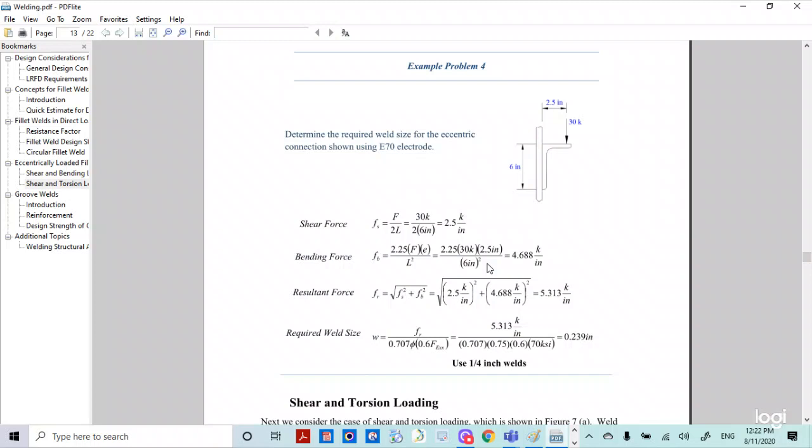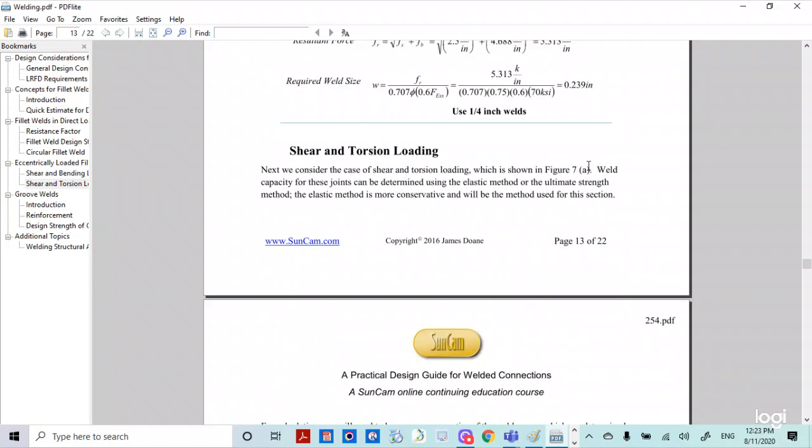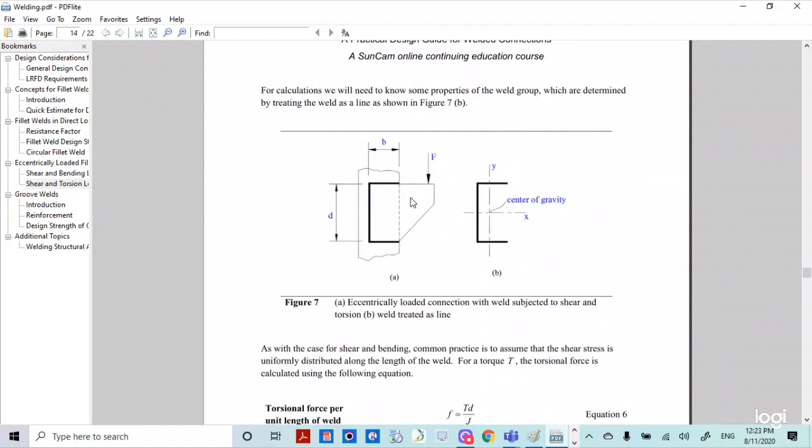The welding must withstand it. The designer must consider the shear force and the bending pressure in the design. So from this diagram and this equation, you can see the problem. Bending and shear force are acting on the component, and the welding appropriately must withstand those forces.